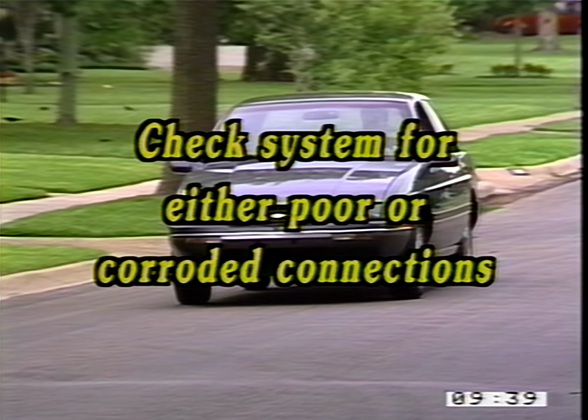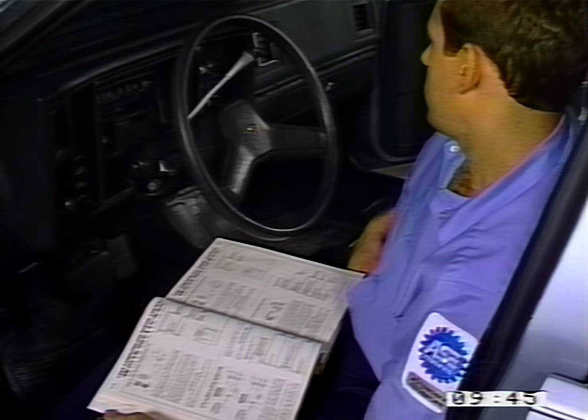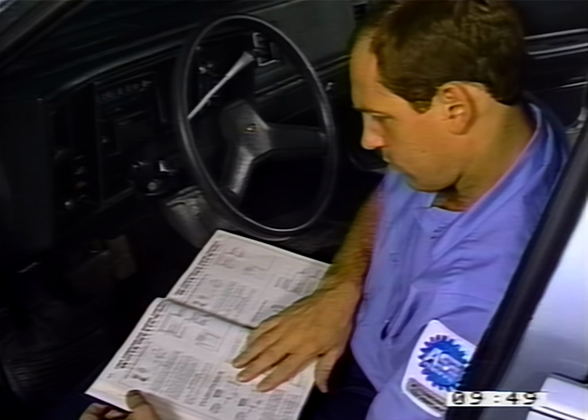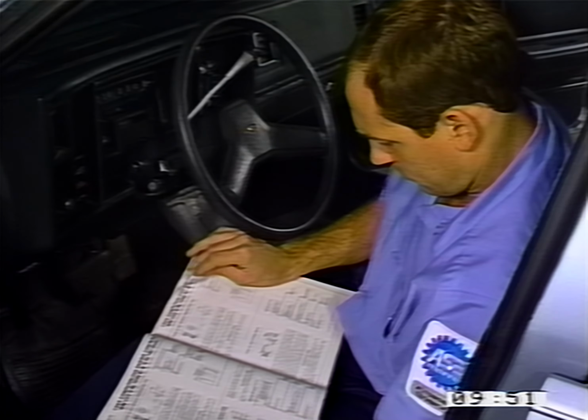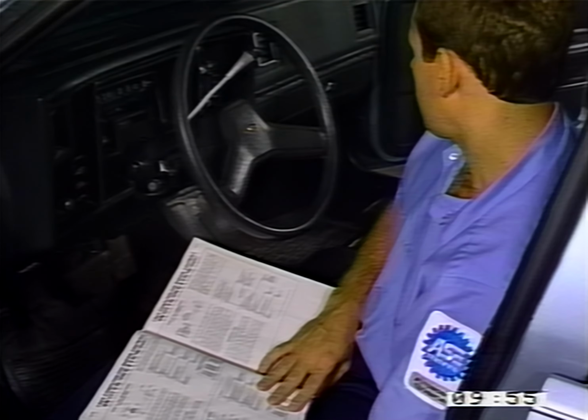The system is then checked for either poor or corroded connections. If the codes reset, start with the lowest and follow the appropriate diagnostic procedure to figure out the problem. The codes are then cleared and the vehicle driven after each fault is repaired.